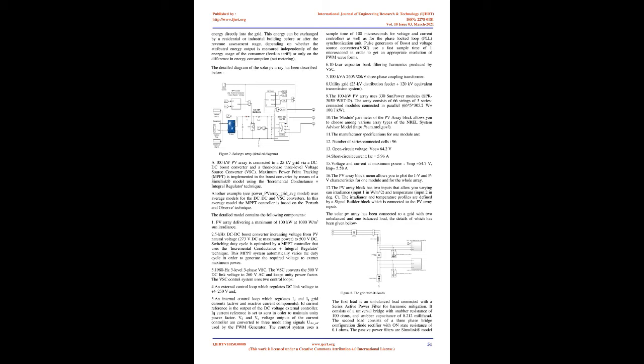A harmonic current source is represented as a Norton equivalent circuit, and it may be implemented with a pulse width modulation, PWM, inverter to inject a harmonic current of the same magnitude as that of the nonlinear load into the system, but of harmonics of opposite polarity. A shunt connection is shown in Figure 5.